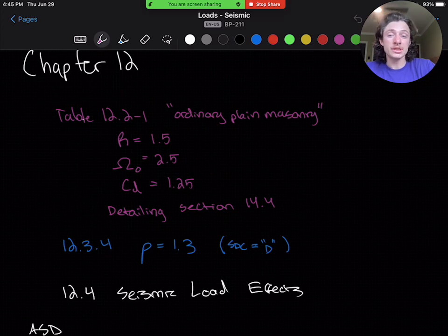And remember, we're using these values to turn our ground motions into a static analysis, or static loads onto the structure. So it doesn't consider the inertia of the structure. So we use these factors in conjunction with the weight and acceleration in order to estimate forces.